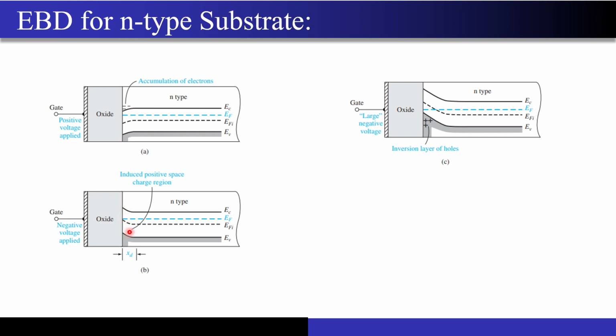If there are a lot of holes over here, then the gap between the Fermi level and the valence band has to shrink, right? Because the more p-type doping you do, the gap between the Fermi and the valence level will continuously reduce. So if I look at the bulk, the gap between EF and EV is large. If I look at the surface over here, the gap between EF and EV is reduced, right? And it makes complete sense, right?